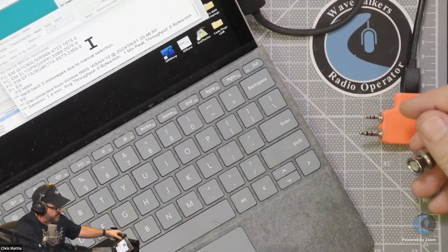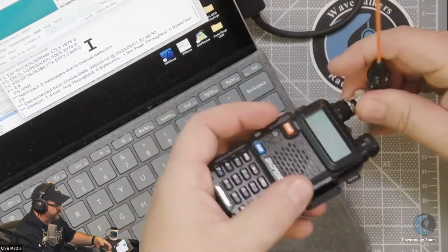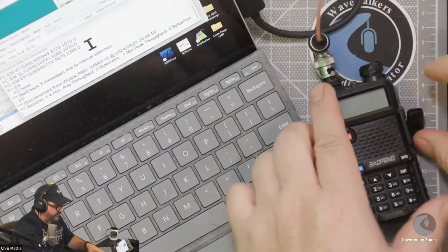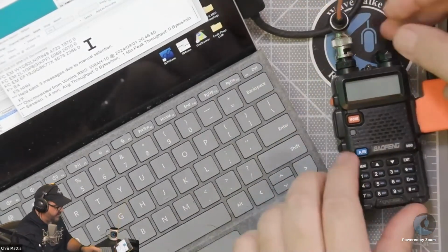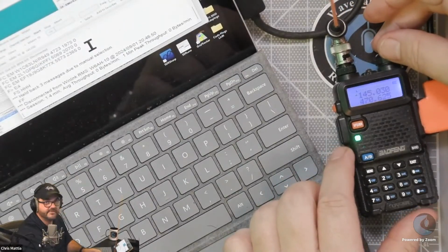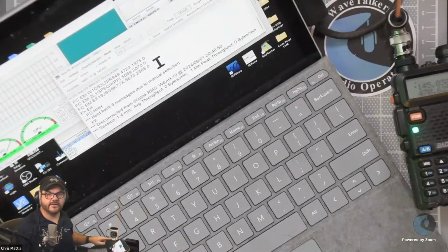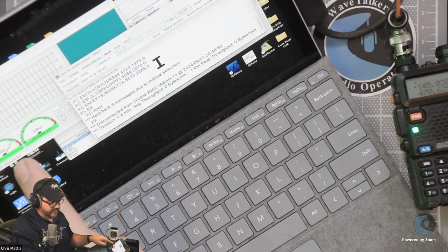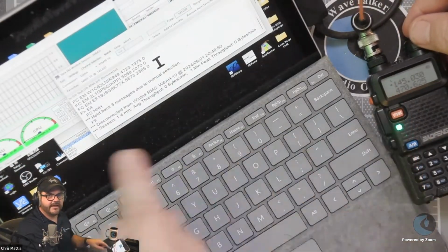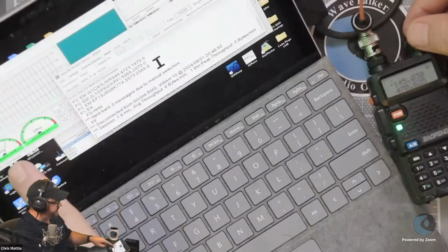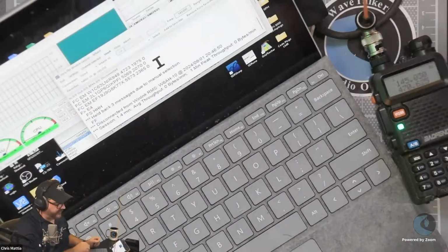And I've got a couple of other radios here. So for instance, here's just your basic Baofeng radio. It's a little UV5R. Go ahead and put the antenna on that. And I'm going to connect the AIOC to that radio. And I'll turn the volume on. And as soon as I do, you can see that my levels indicator jumped up to the right level. Again, I can adjust the level on my radio just using the little dial here at the top, and I can fine tune this until I get my receive levels at exactly the right amount. All right, so I'm all set there.